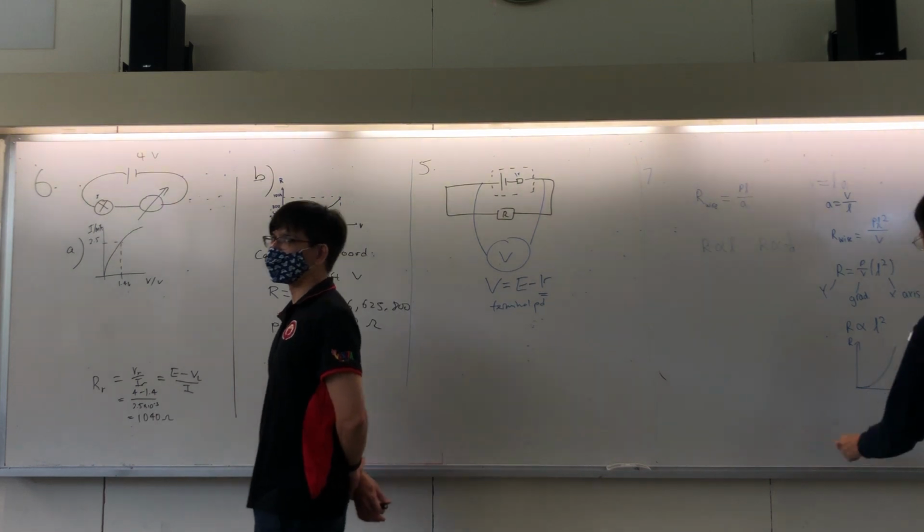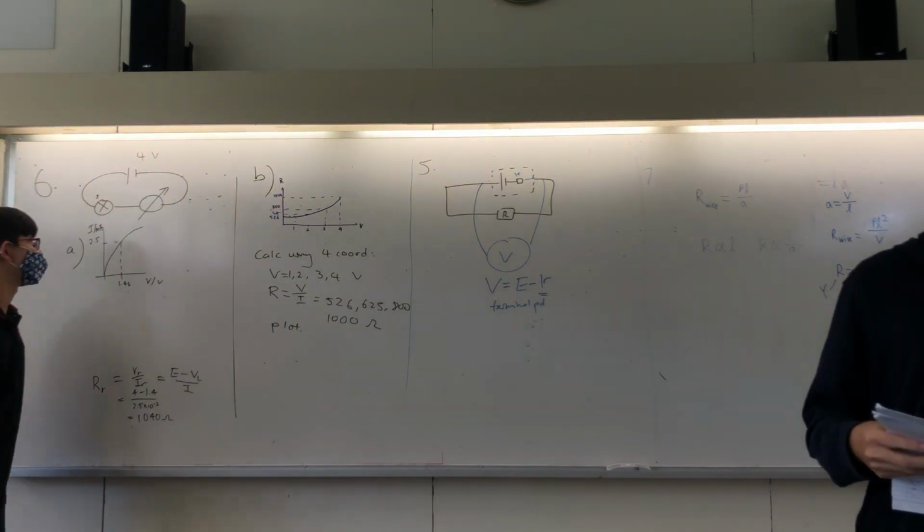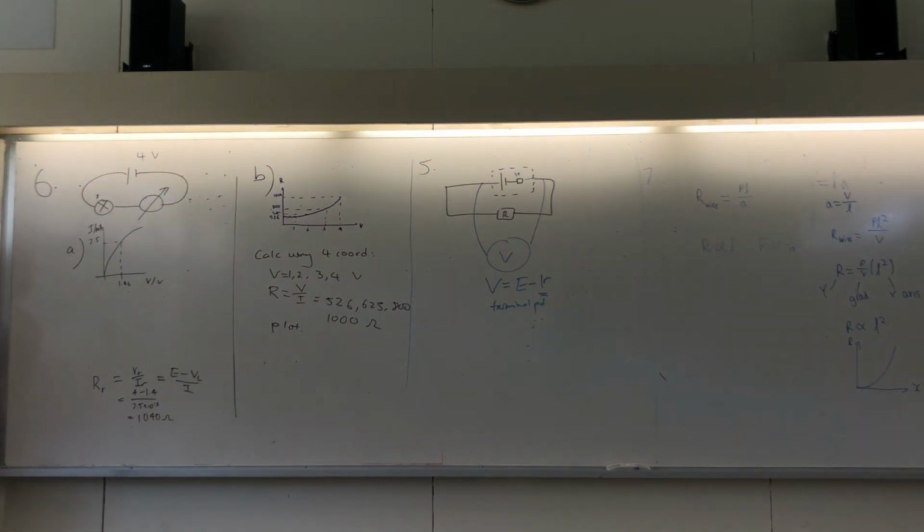Okay, let's take a look at the work that has been done. JJ did question 6, so JJ, you explain yourself. You read the resistance off the graph. They want the resistance of the variable resistor, not the lamp, right? So after you read the current off the graph, then you just use R equals V over I. But I don't know V.